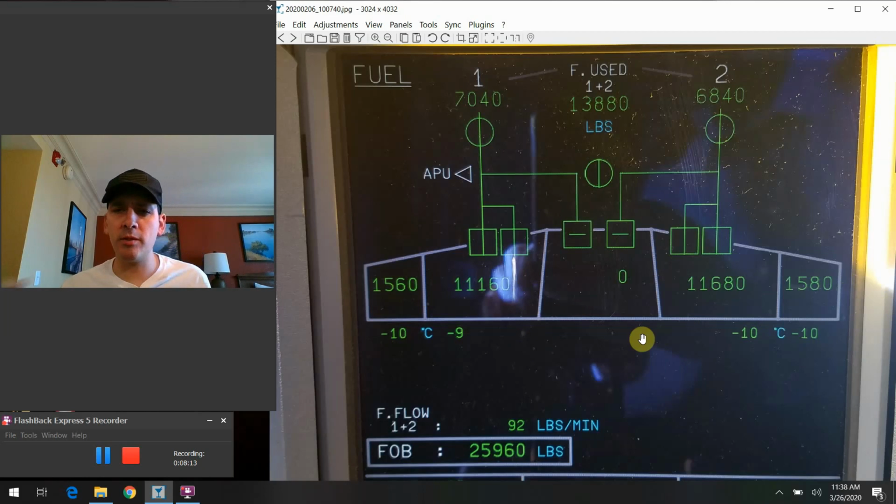So just to back up also, to give the basic explanation about why they situated the system in such a way. They just want to leave some amount of weight out at the outboard portions of the wing, and this is a structural kind of relief thing for the airplane, to allow for some balancing to be done, not aerodynamically, but physically. You have this extra weight just hanging out at the wings there, so they're not bending up unnecessarily as the weight of the airplane changes and all this kind of stuff. So kind of a structural thing. Hopefully that makes sense to you guys.